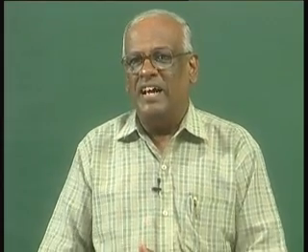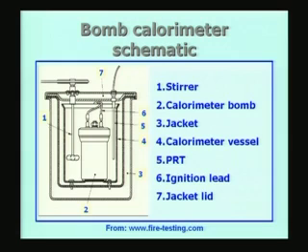Okay. Usually an iron wire is used and the wire itself is going to melt because of the high current which is going to go through that, and during this process it is going to generate enough heat, enough temperature to start the reaction, and the bomb is filled with, as I said, pure oxygen at about 25 bars.